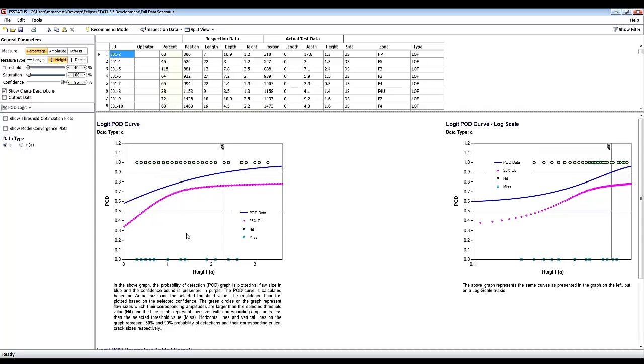So here in this graph, that is probability of detection, the blue curve shows you the probability of detection of any size. So for example, if I want to know what is my probability of detection of a defect with height of 1 millimeter, I go to 1 millimeter here and go vertically to the graph, then horizontally to the side, and I would see some number around 0.8. It means that with this technique that I use and this input, there is 80% chance or probability that I can detect the defect with the size of 1 millimeter.